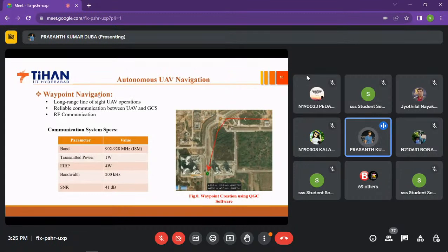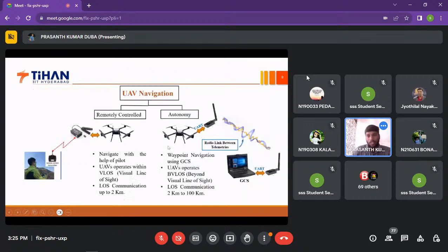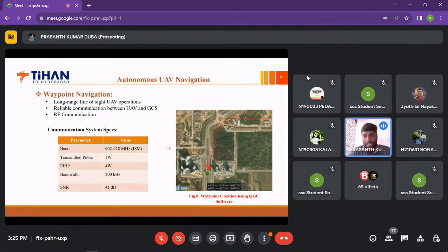Calibrations include the GPS and the compass inside, so we need to do compass calibration. One more step is axial calibration. If I put my UAV facing forward, which is my forward direction, then I slightly tilt it left, and I have to train my system for left, then right, and up and down. We have to do this calibration before any flight. So these are the basic things we need to do in the calibration step.